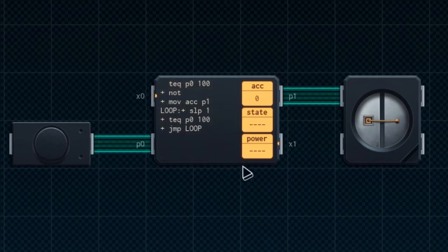Maybe some of you are already able to see the problem in here, because this instruction will get executed. And since the button is released, it will fail, so it will not execute anything in here. So it will never sleep, because there is no sleep instruction. So what we can do is to just add a sleep down here at the end that always gets executed. Another possibility is to just get rid of this plus sign. So the sleep happens no matter what the input is, which is a better solution in my opinion.